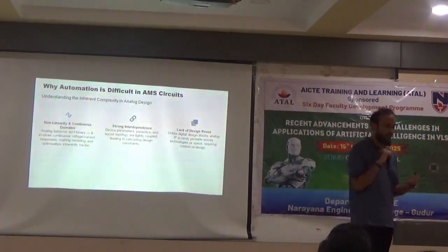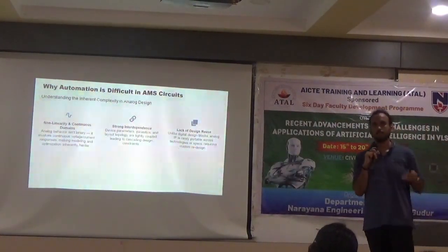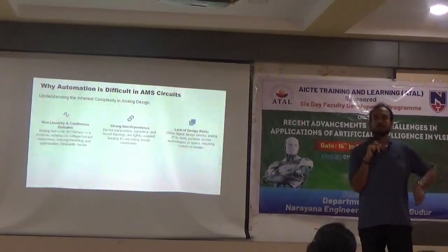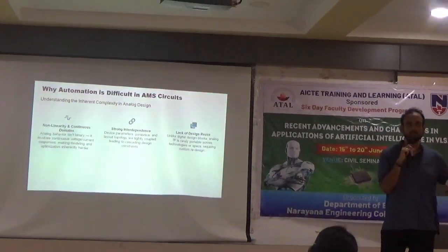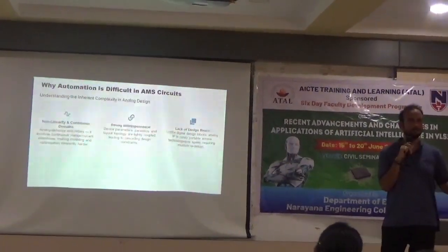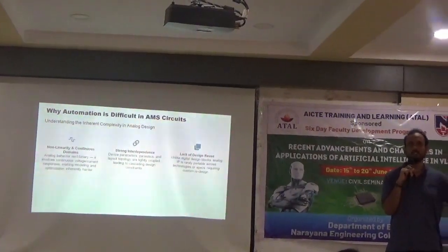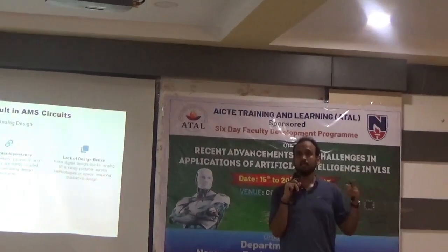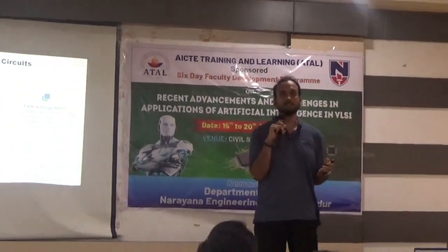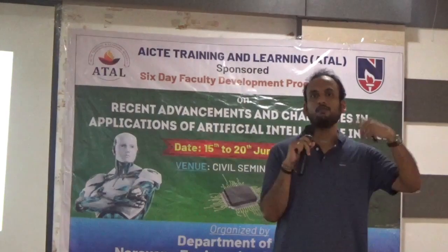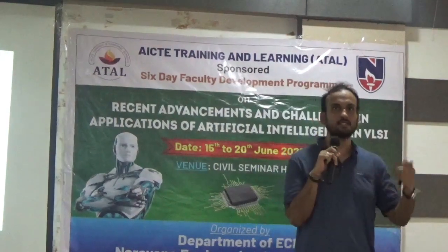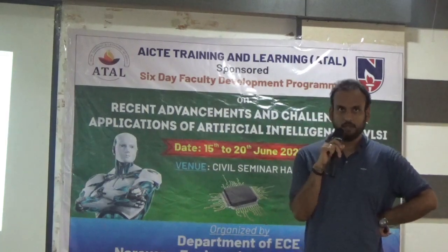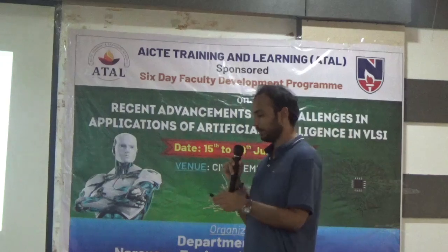In industry as well, we have a lot of engineers who are working on the schematic side. There are a couple of engineers who are designing the layouts and so forth. So all these stages are interlinked together. Once you start your schematic first, then you have to optimize it in such a way that when you do the layout, you should get your desired spec. So while designing the schematic itself, in your mind it should be there that some parasitics would come into your layout, and you have to account for these parasitics in your design. This is how you should proceed. And this is a very good case for the role of AI in analog design.